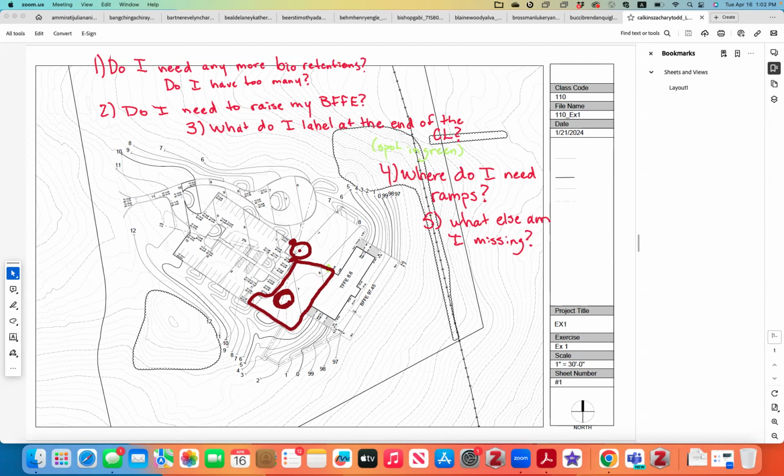This one is not receiving a lot of water unless you use a trench drain, right? This is the drainage area for that one. That's pretty small. So I probably would either put a trench drain in and have the trench drain direct into the retention, or I would just cut holes.